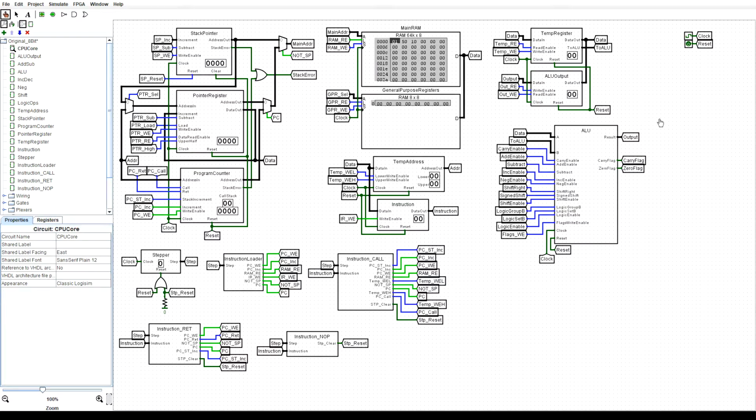And since I botched the recording, I might as well show you what's going to happen. I'll go through this slowly, so we can see the signals here, which are set to get the data out of the RAM and into the various locations. So we do the clock, and the program counter increments quite nicely as we load the data into this register. And then finally, we call our function, which the size of this function is 1 byte. And it's a return instruction. So if we do this, it just sends us back to where we were and loads the next instruction, which is a no-op, which does nothing.